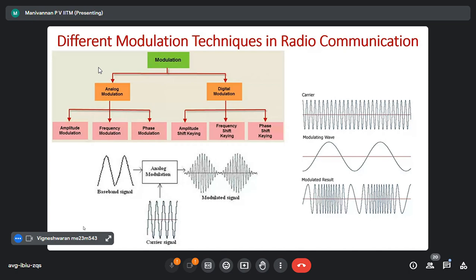Sir, you have told that basically there is a base signal which is to be transmitted to the destination. Correct. Now, since the base signal has low frequency, to transfer that we would need a very big antenna, which is unrealistic. No, without modulation, if I transmit without modulation, then antenna, antenna both should be very, very big. Right, sir.